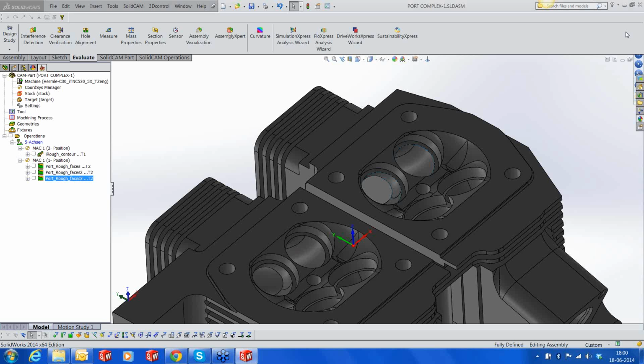In such cases, you can't use spiral because the spiral will produce a scallop which can obstruct these gases, and thereby your performance of the engine goes down. In such cases, we can use what we call plunge finishing. So on one tube, I'm going to show you spiral, and on the other tube, I'm going to show you plunge finishing. Okay, there's another question.